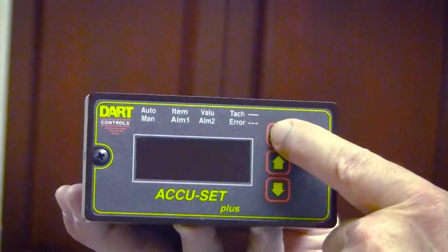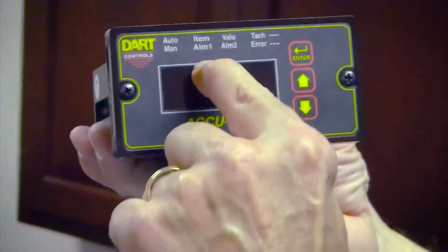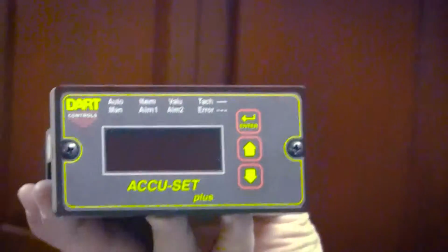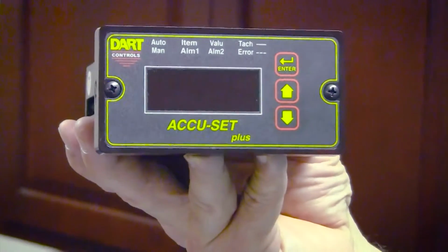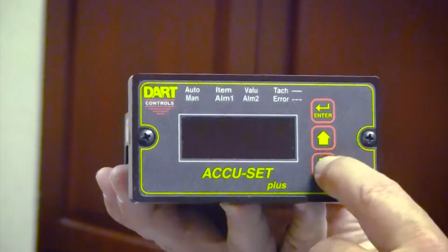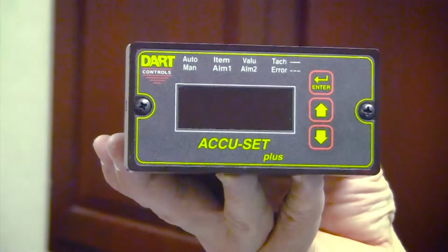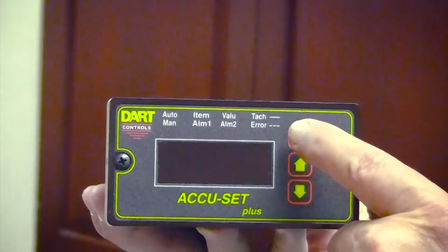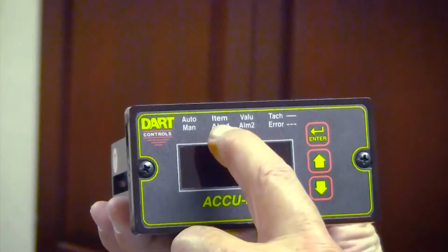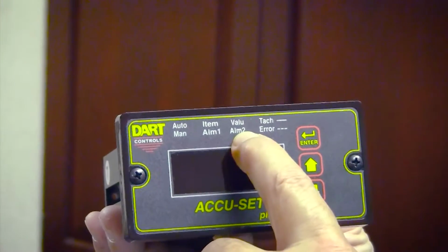You press and hold the enter button, and what will happen is this item light will turn on solid, and you'll see only a 0 in the window. That means you're at item 0. You use the up and down arrows to navigate the item list. When you get to an item you want to change, you press the enter button. The item light will go out and the value light will come on steady.